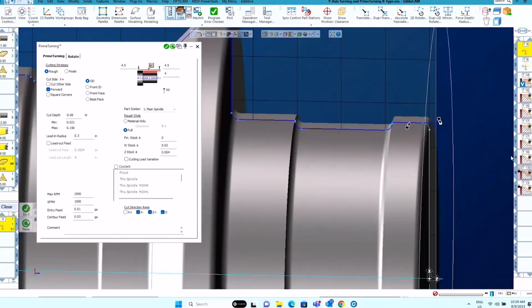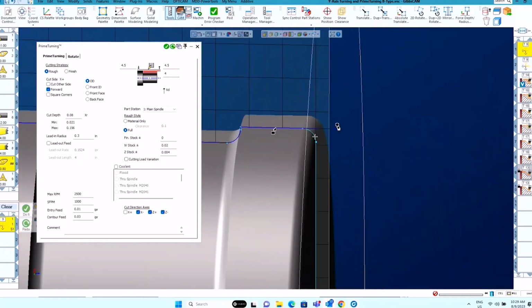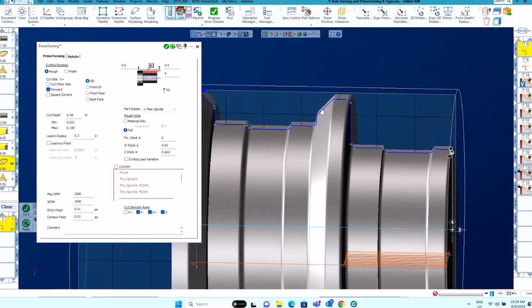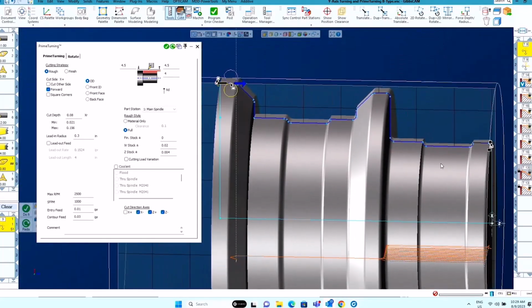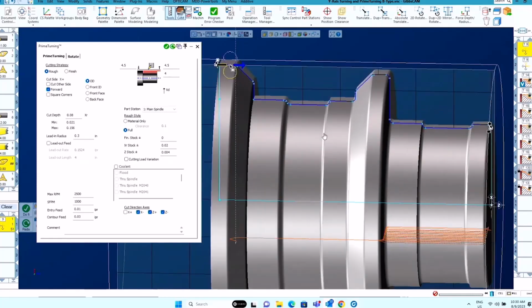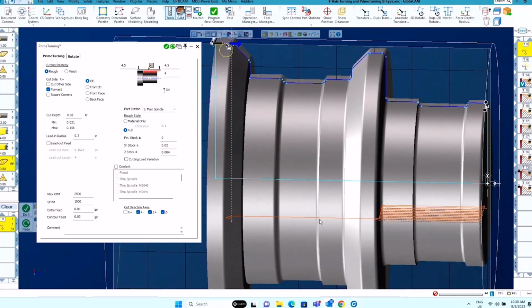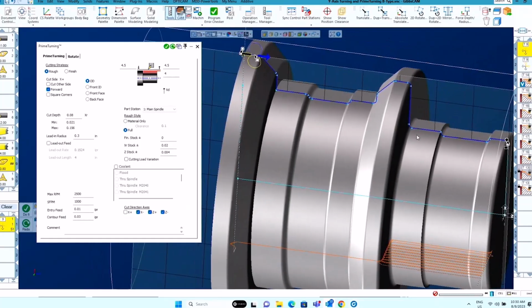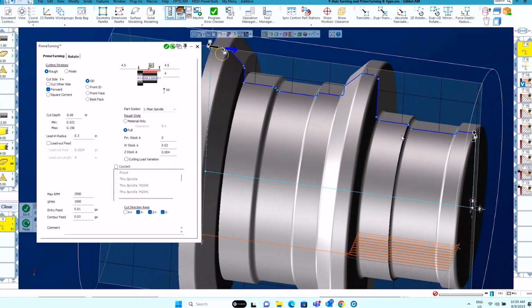Actually, let me correct that. I'm going to set it to that radius. So I can come down here, and this is my end marker. So I want to machine the part all the way across here using our prime B insert. One other thing: I don't want to dive with our prime B insert into that valley over here. So I take the X plus away from it. It says, stay away from that area. Don't dive with the insert into that area down here.